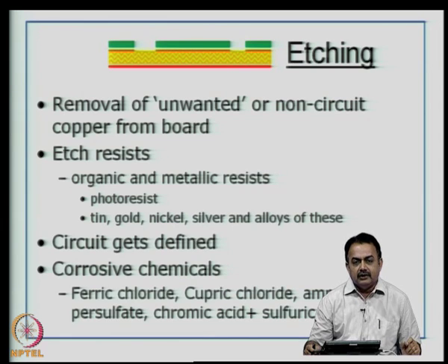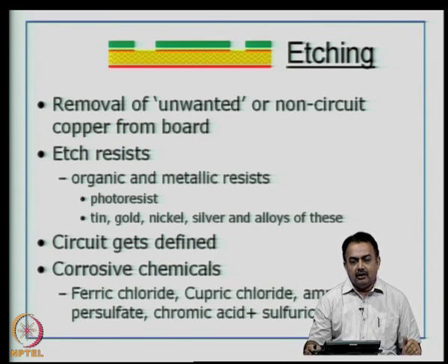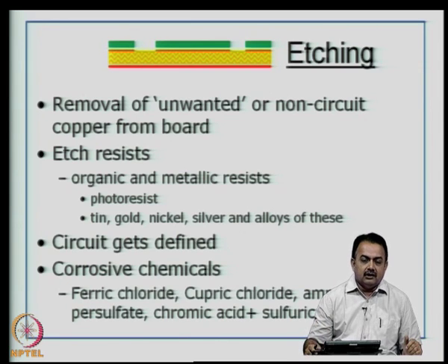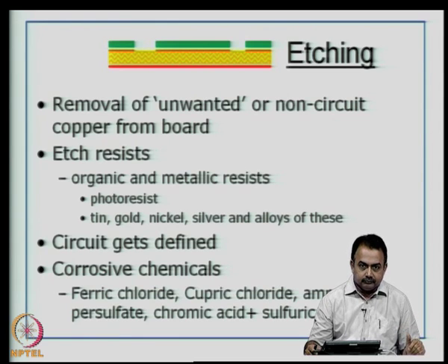The reason why we use nickel as an undercoat of gold plating is that if you directly plate gold onto copper, after some time or during its operation and based on the environmental factors and so on, and also due to the inherent crystal structure and properties of copper and gold, gold can dissolve into copper interstices, and therefore, after some time you will see that the thickness of gold that you have plated is gradually reduced.